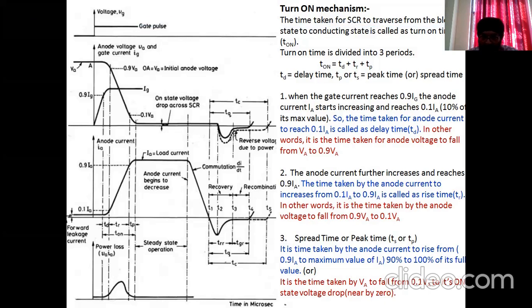But due to a large value of charge carriers accumulated in the capacitances in the junctions, we have a large inflow of minority charge carriers on the other side, in the negative side of the current, due to inertia of all this. And now this takes some time for recovery.